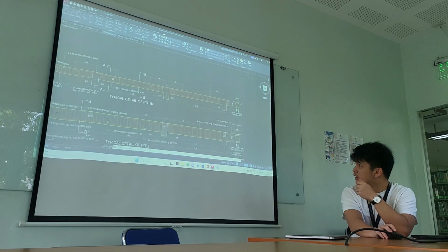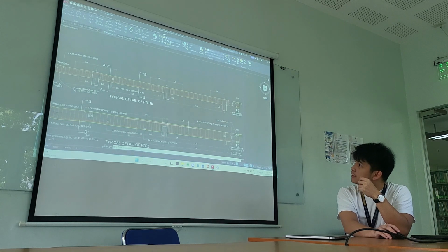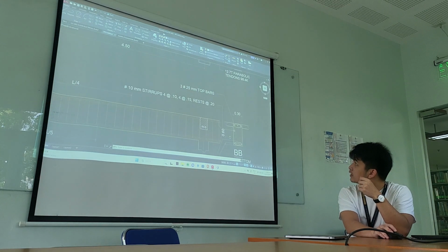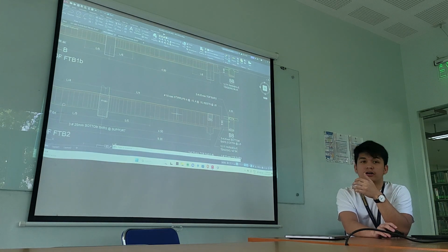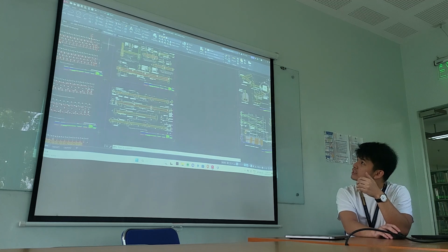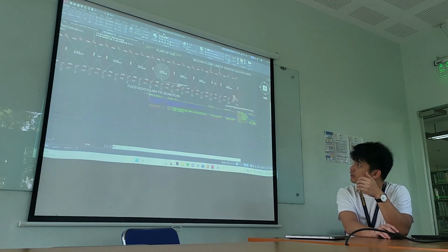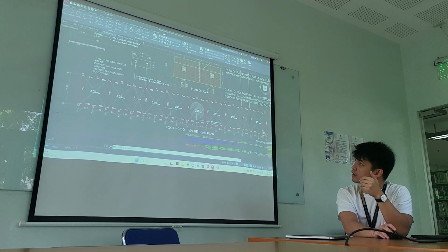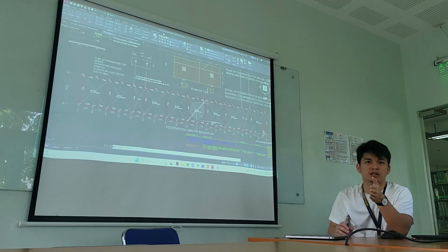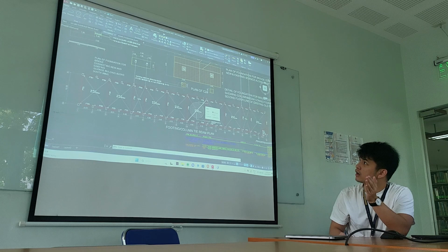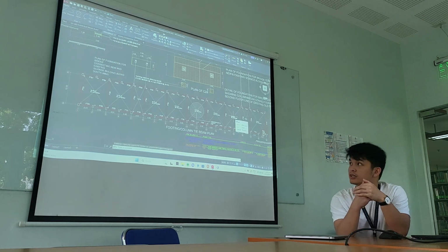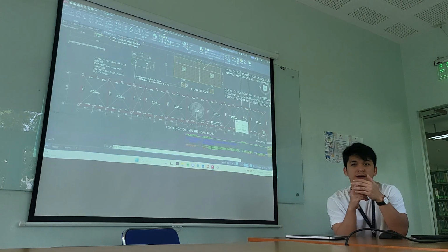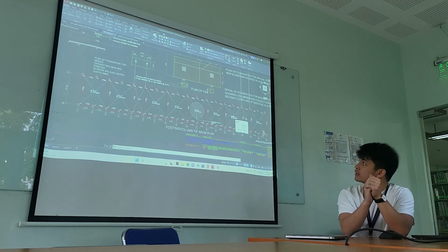But the FTB2 beams are 0.6 in depth, and contain 8 bars for the beam. As indicated here, the top and bottom beams are FTB1, but those that are for its height or depth, this one, are FTB2 beams. Considering that it has a larger span between columns, it is understandable that their depth is much greater compared to FTB1 beams.